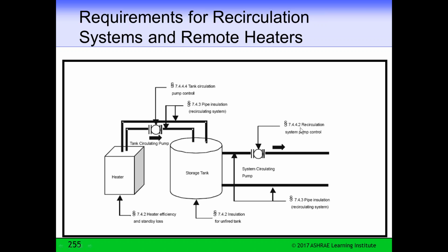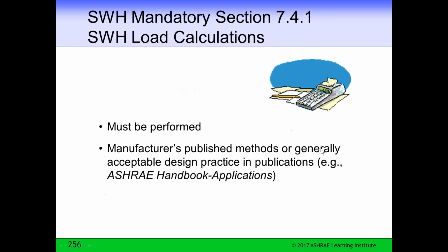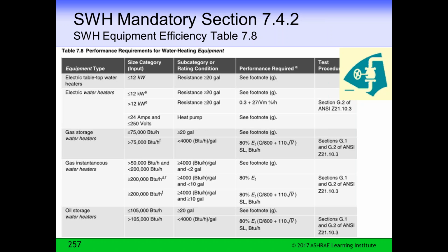We also require that load calculations be performed so that you know exactly how much water is required. Again, we do not require you to size your system directly from that load calculation. You have the capability for some engineering ingenuity to play with that design.